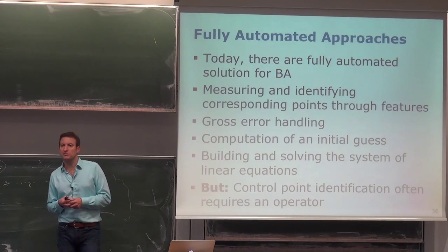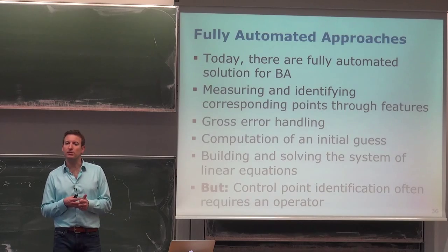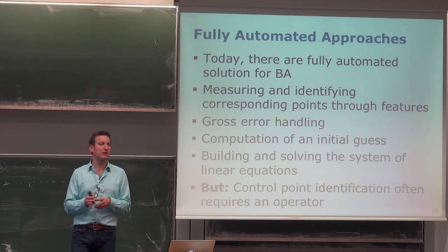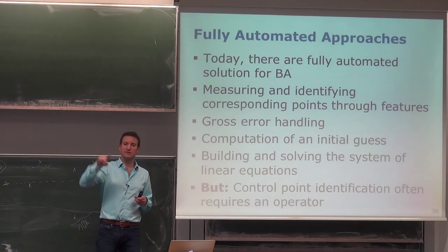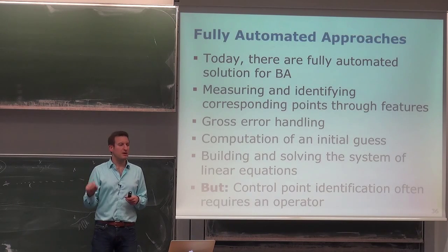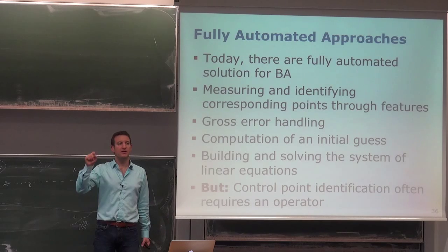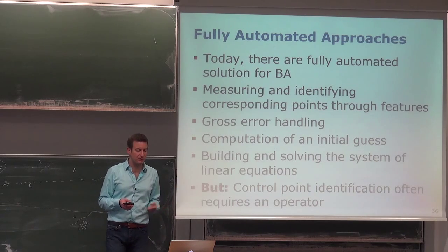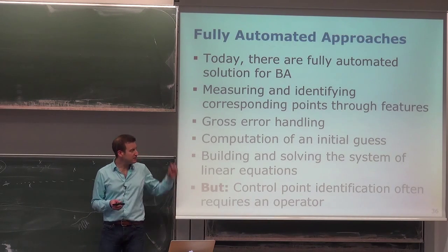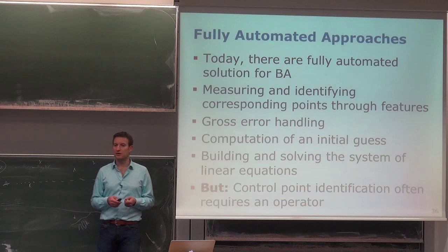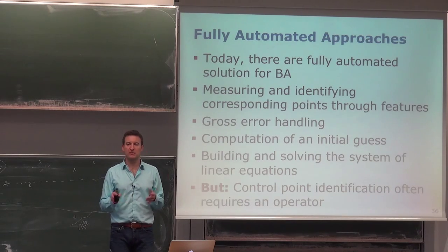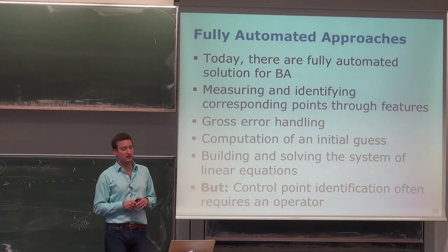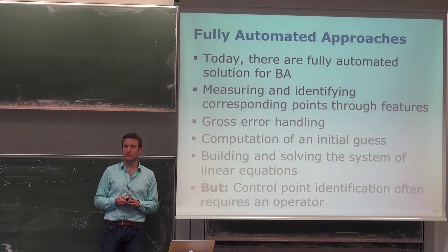What is typically not automated, if you have existing ground control points, is that you often still need an operator who creates the correspondence between the measured ground control point, which has been measured with external sensors, and the locations in the images. This can be one source of errors, making wrong data associations, but this is a process which is typically done manually. The rest is a more or less automated process, maybe with some manual checks, but most of the components run as a batch process.